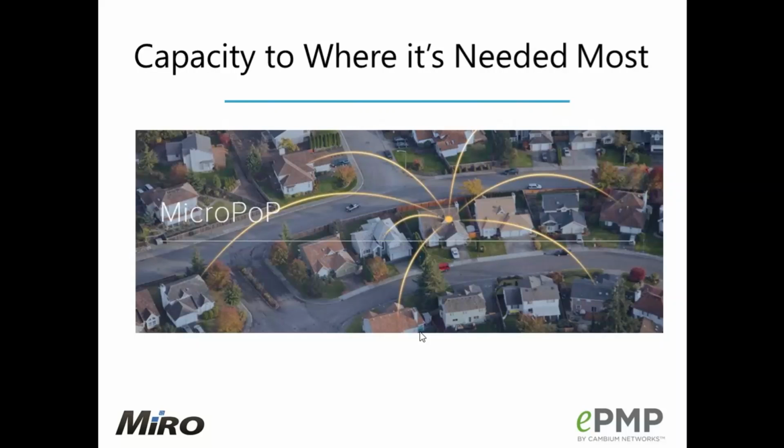You'll have 802.11 AC Wave 2, be able to push up to 1.2 gigabits per second, and of course with that 4x4 MIMO, that base station will communicate with 2 subscriber modules at once. So you're really doubling up on your speeds just based on that functionality.